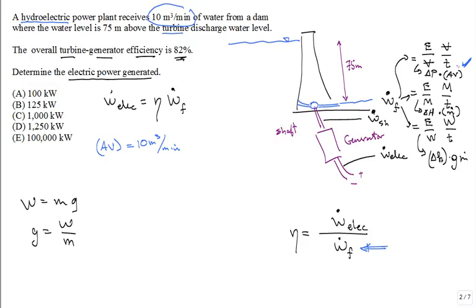Maybe I can use that to get the mass flow rate, which is just rho A V. So I could come down to one of these forms, which would also be very convenient to use. It looks like I multiplied by 1,000, so it's 10,000 kilograms per minute. That's the mass flow rate, true? Because the density of water is 1,000 kilograms per cubic meter.